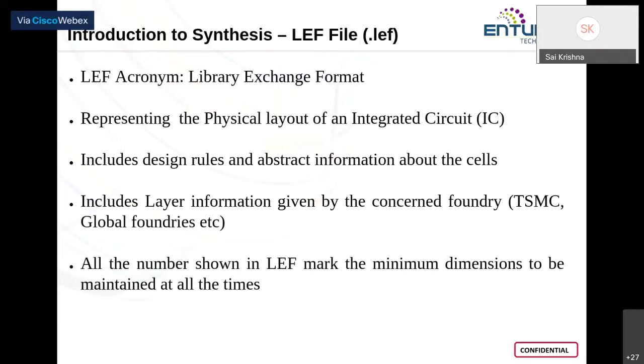So apart from these three, this is just for your information. If you are using logical synthesis, you'll be taking only RTL code, Liberty file, and SDC. In case there is another form of synthesis called physical synthesis, which is very much analogous to physical design. To keep it simple, physical synthesis is like running a rough estimate on your physical design. So when you're dealing with either one of these stages, you include dot LEF.